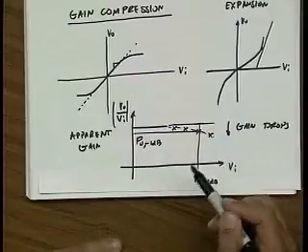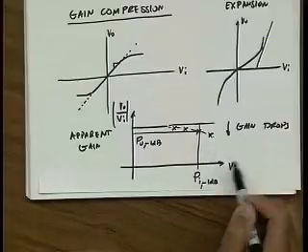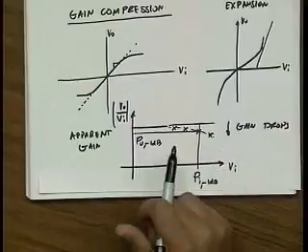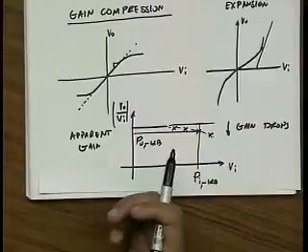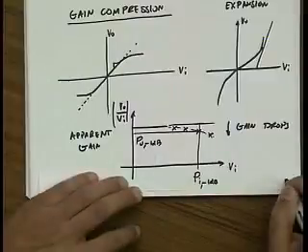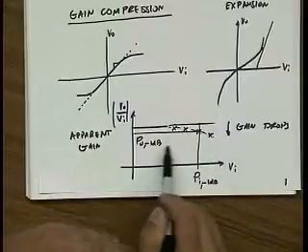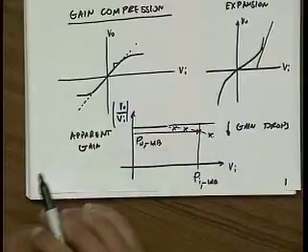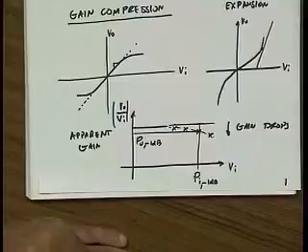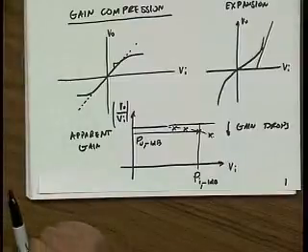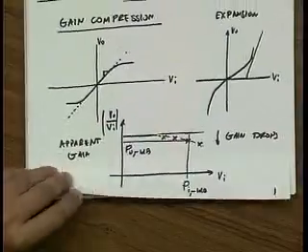Now the reason that we don't like to operate an amplifier beyond compression will become very clear in this lecture. So it might seem, sure, just use an amplifier out here, you're going to get less gain, but it's still a good amplifier, right? No. We'll see today why we don't want to use an amplifier in this region. So well below the 1 dB compression point, that's the small signal region where we like to operate an amplifier. Okay. Questions or comments? All right.